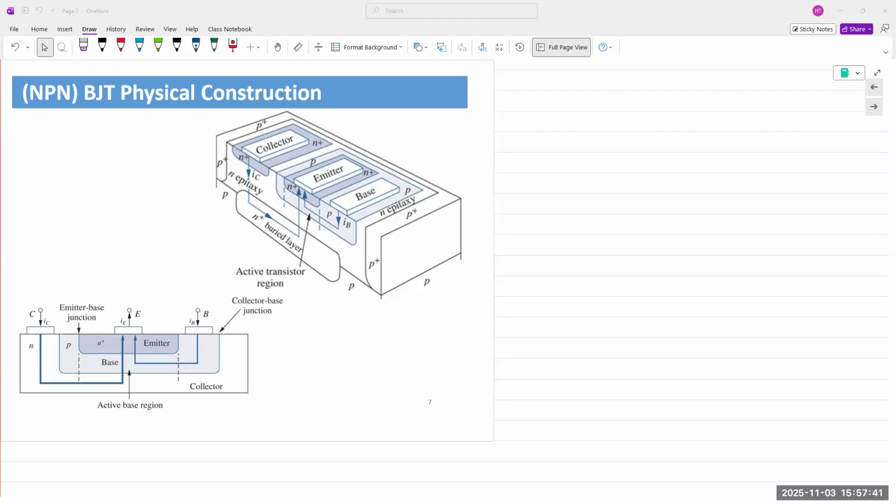And that's the function, that's the gist of how a BJT operates. You have an emitter-base junction, you forward bias that junction. When you forward bias the emitter-base junction, the charge carriers are going to cross over into the base. Into the base, they are minority carriers. So the second junction, you reverse bias. When you reverse bias the second junction, the minority carriers, which are excess in the base, are now able to cross over the second junction, and a huge amount of current starts flowing out of the collector.